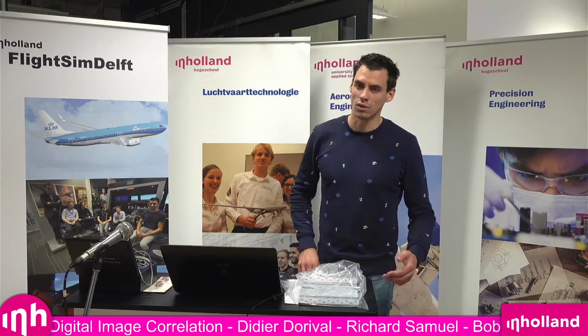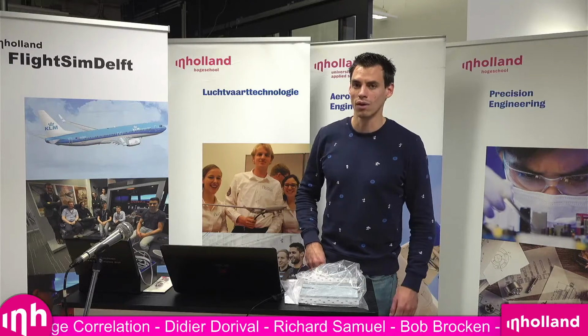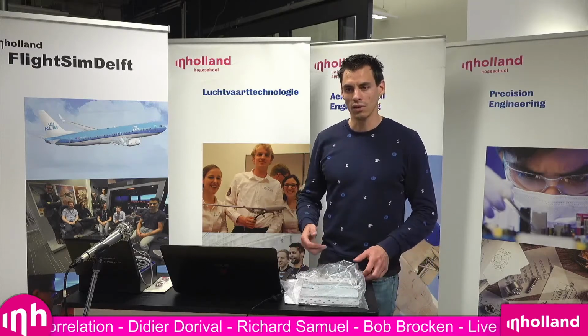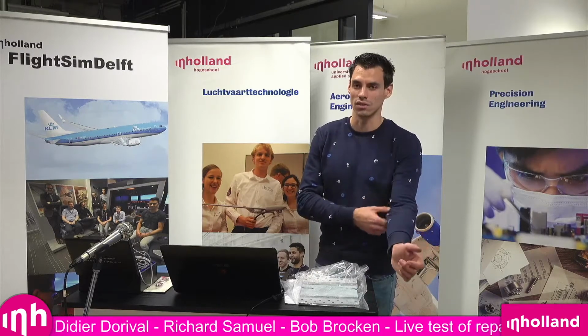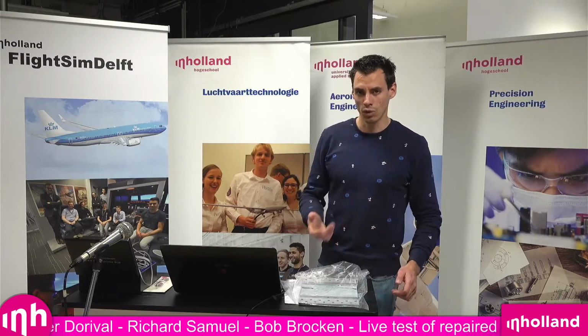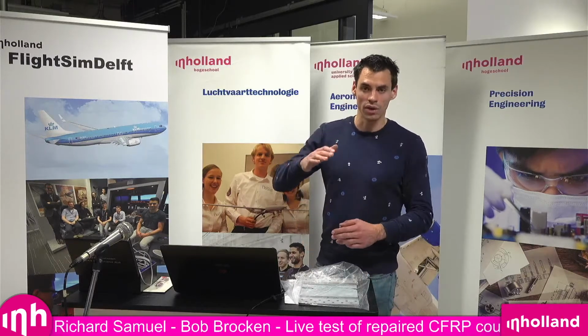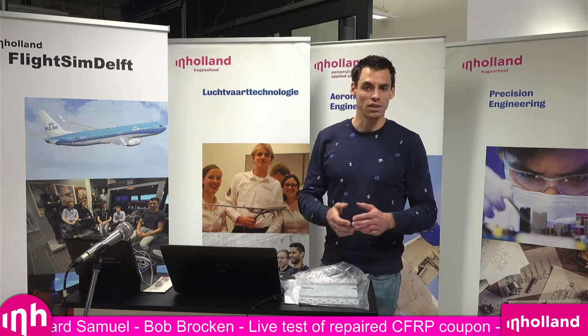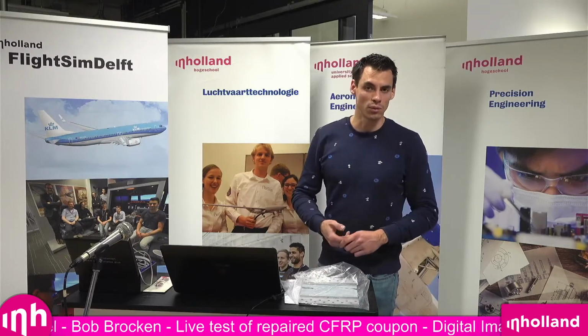So we get resolutions of about 0.6 micrometers, which is very small. And generally, I feel like we can replace our current extensometer with the DIC system, especially since it gives much more information than just the extensometer. The extensometer measures only in one direction, whilst the DIC system does a full strain field. So we can also immediately determine the Poisson ratio, for example.